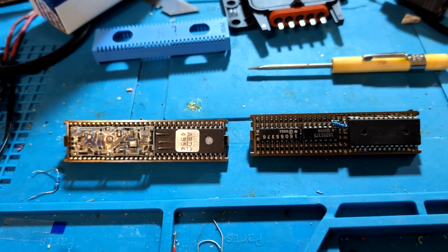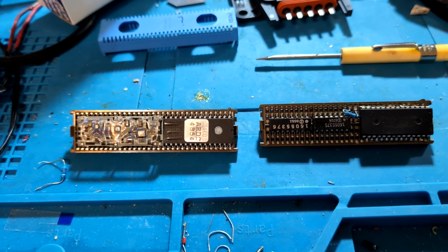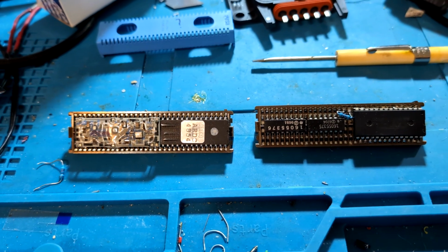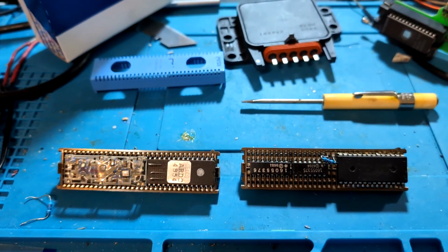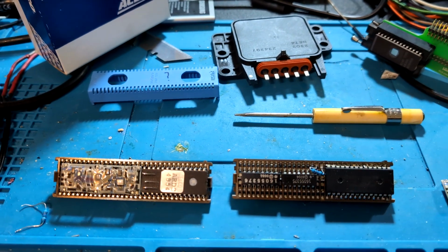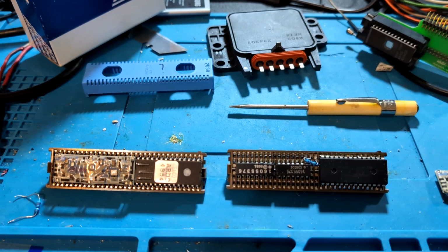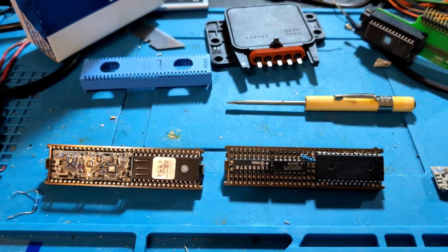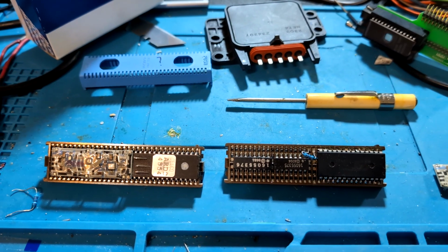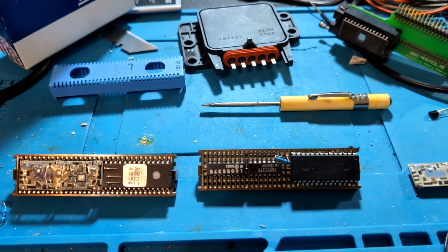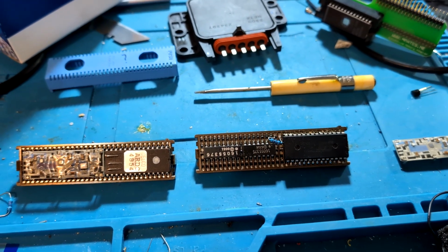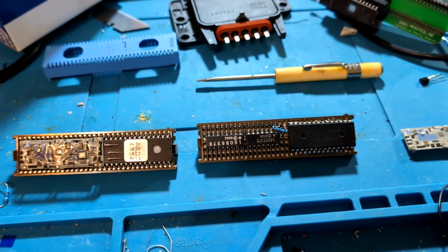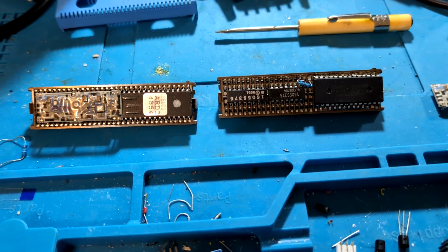So when you switch the computers from a MAF car to a speed density computer, unless you go ahead and change that knock sensor as well, your computer is going to be expecting to see a 3.9 k ohm resistance in the knock sensor circuit, and if it doesn't see that, it's going to throw a check engine light, and the knock sensor and the knock circuit will not be working.